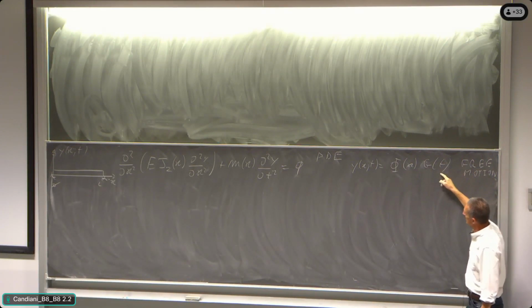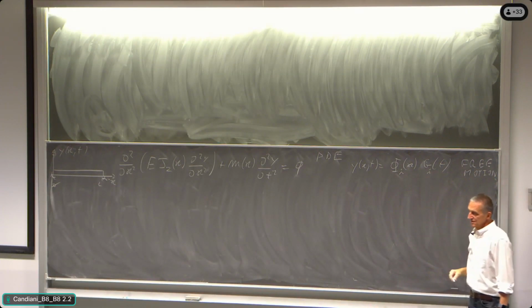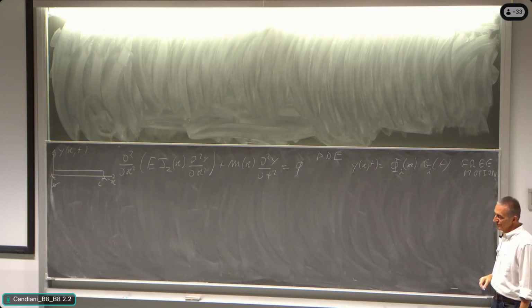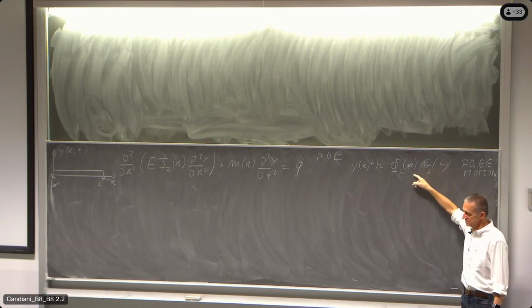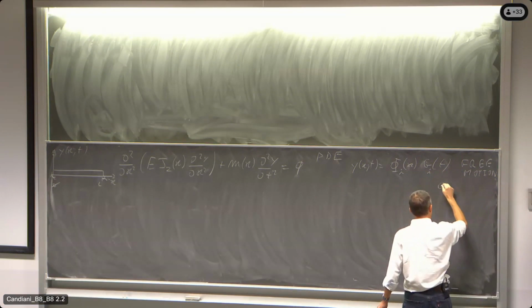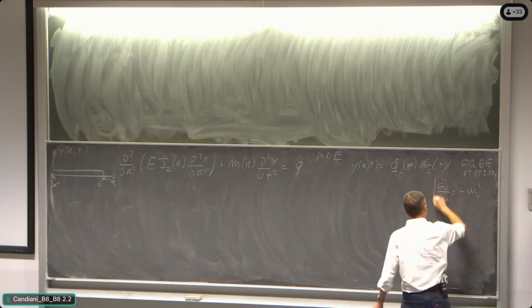And those are actually the harmonic functions that are representative of the free motion. And so they are harmonic functions that are oscillating at the natural frequencies of the modes, all right? And in particular, g_i two dots divided by g_i is equal to minus omega_0i squared.